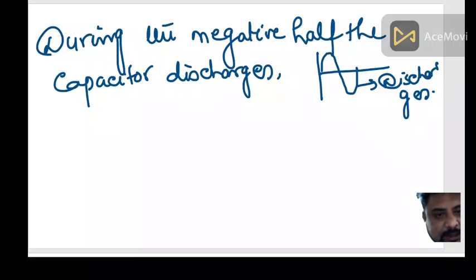So the capacitor basically opposes any change that is occurring in the voltage. Now try to understand this. When it is connected across a pulsating DC voltage, pulsating DC voltage means that the voltage is not constant. It has some AC components, some components that are changing. The capacitor opposes all those changing components in the output DC. This is the mechanism by which it filters out the AC components.